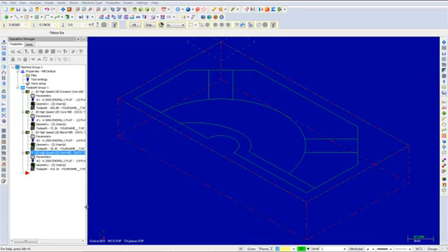In this step, you will learn how to copy an existing toolpath in the Toolpath Operations Manager. You will also learn how to rechain the geometry used in the toolpath. First, we will copy the previous operation. From the Toolpath Operations Manager, select only operation number 4. Ensure that this is the only operation with a green check mark.